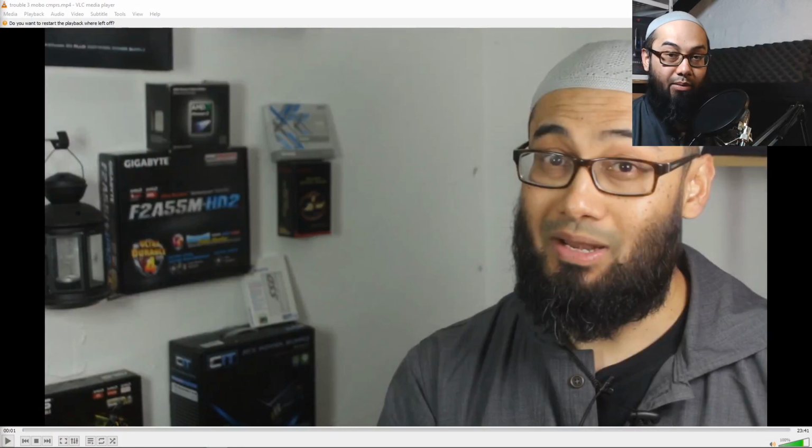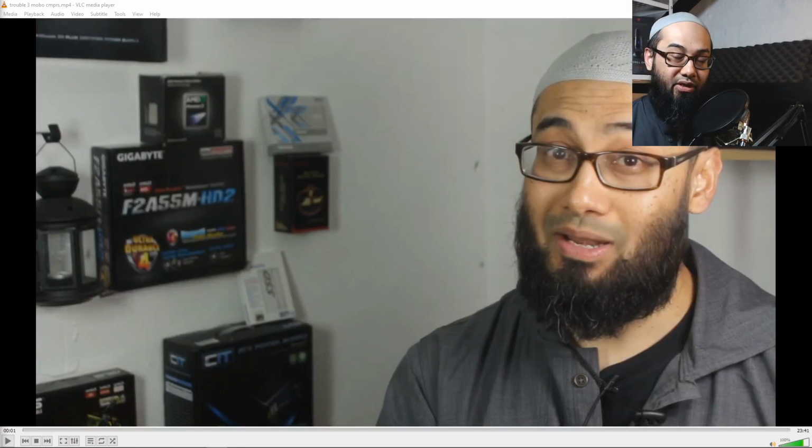In the future, I'm going to redo the series. The motherboard is an important thing to troubleshoot, but in terms of accessibility and ease, it should be the last thing you want to get your hands on. If there's any problem, you should be breadboarding the whole thing, meaning removing it from the case, once you've eliminated other problems like the RAM, graphics card, cable connection, power supply, yada yada yada.